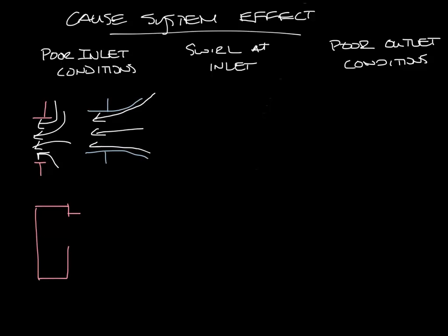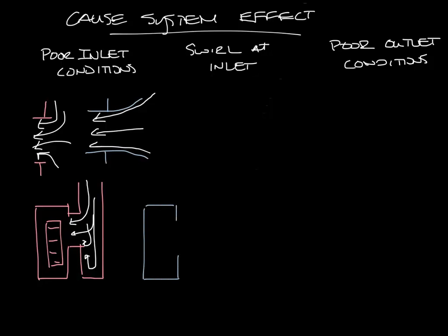Also, let's look at maybe an inlet box going into the fan. So this is our fan, and our ductwork comes from up here, and we've built an inlet box, but it goes all the way to the floor. The airflow can come down, but down here in this bottom, you can get turbulent airflow where the air is going to swirl around and give you bad conditions. A better option would be a fan like this, and then with a nice kind of elbow coming in to direct the air into the fan.